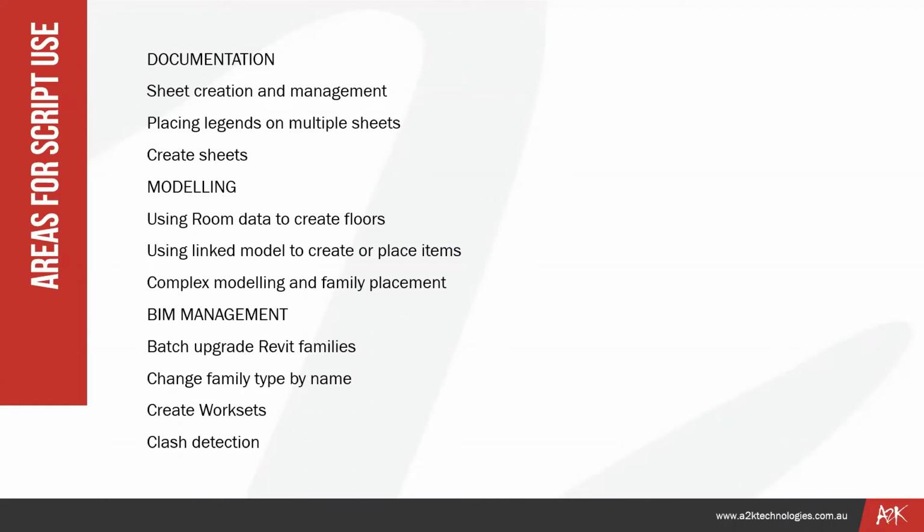You can also do complex modeling and family placement. Now, this is where I was talking a bit before about using Rhino and Grasshopper. A lot of that you can do in Dynamo itself, and placing of complex families. So if you were going to do bridge families, or even a roof frame or something that may change, where you're really getting into your parametric, you can put all those parameters in the family and then place those nodes through Dynamo to basically create that project.